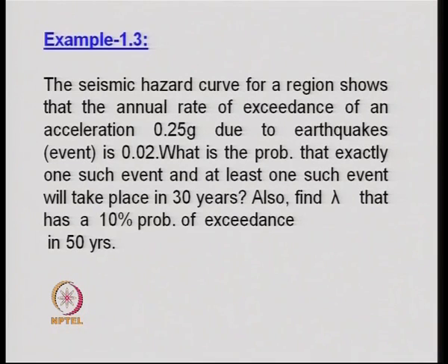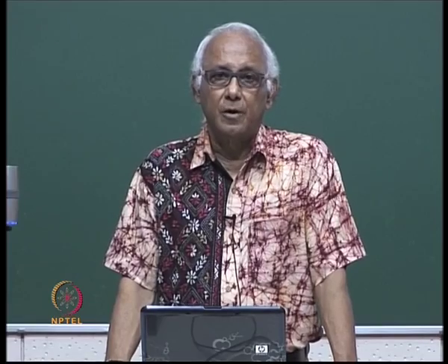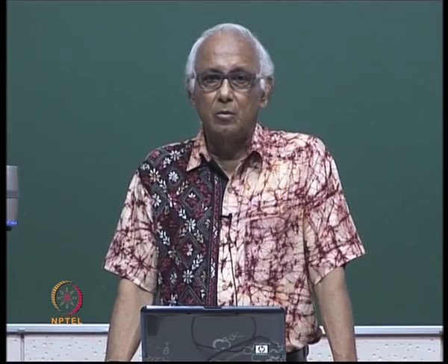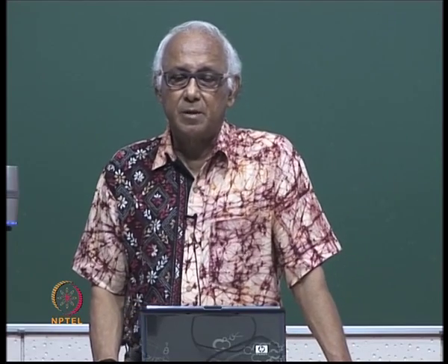We can see that by drawing histograms showing the probability of occurrence of magnitude of earthquake and the probability of occurrence of certain epicentral distance, and using the pertinent equations, one can obtain the seismic hazard curve for a particular region for a seismic measurement parameter.